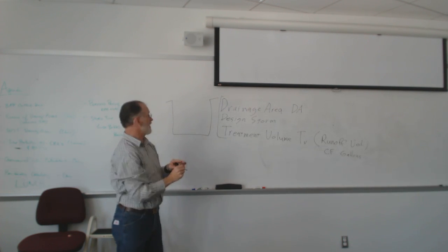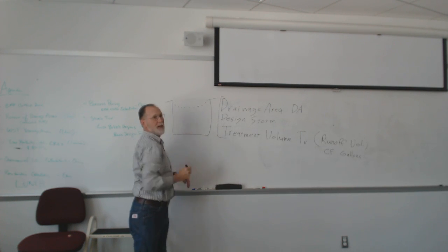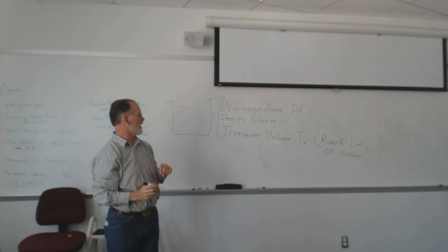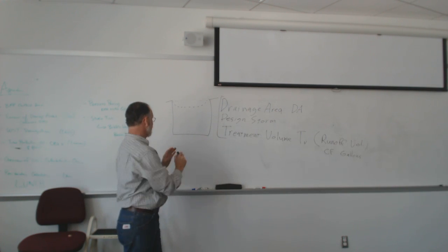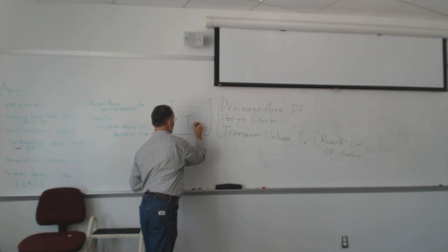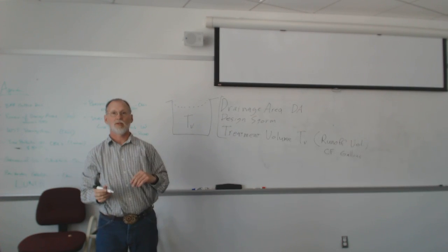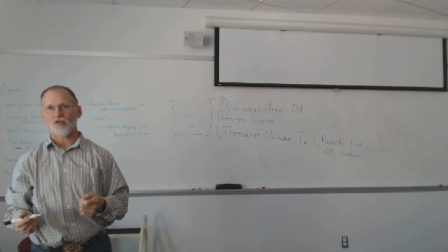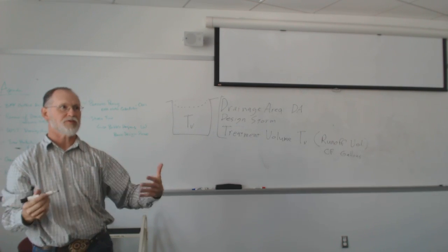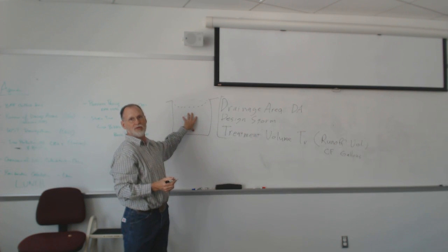It might be a rain garden where at the surface of it, we have a ponding depth, and I'll talk about a rain garden in a second. But we will have some volume, or we'll size this to handle our treatment volume. So whatever volume we decide we want to manage, say the 1 inch storm going to this BMP, we will size it so it can hold that entire treatment volume, if at all possible.